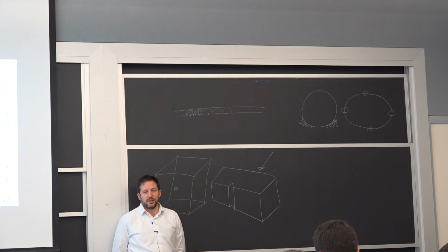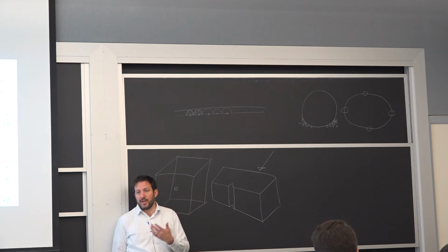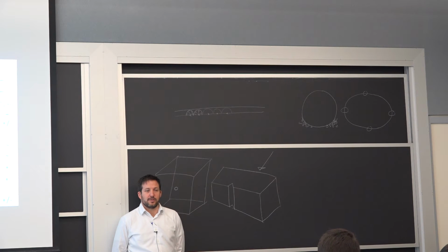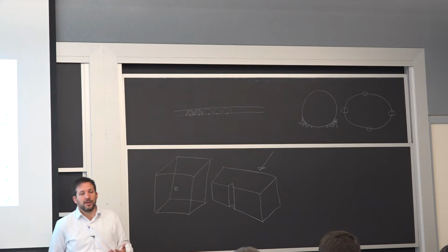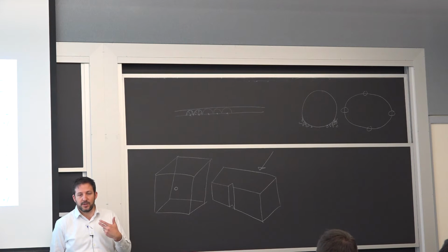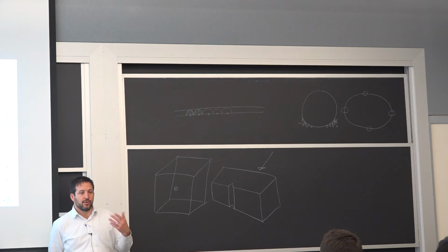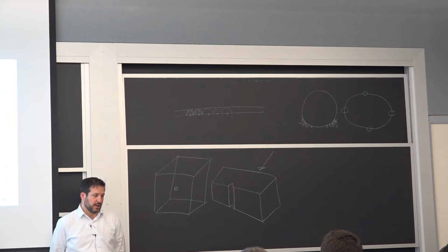Those two, aluminum you can use at very low temperature. If you have a stainless steel with the same type of structure as aluminum, so a face-centered cubic, what we call austenitic stainless steel, that's what you need to use for cryogenic applications. You can't just use a structural steel at such a low temperature. So there's always a limit, and the reason to do these tests is that the limit depends a lot on very small impurities and on grain size. If you're trying to build a bridge or a ship that's going to the Arctic, then you do need that low temperature toughness. Even pipelines, which is something I want to discuss with you in detail, you have to worry about that.